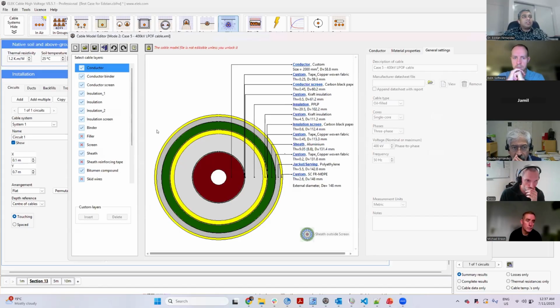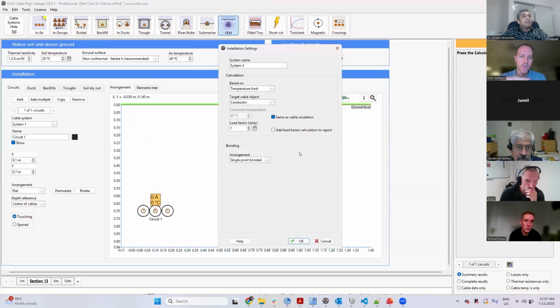You can model your custom cables from your data sheets, and you can save these cable models. And that's the recommended approach, right? We always do provide a database of pre-modeled cables. It's actually the largest of any software package. We're continually adding to that, but you should model cables, especially high voltage cables, from cable manufacturers. Yes, so you could start from one of our cables and then build on that to get your own cables.